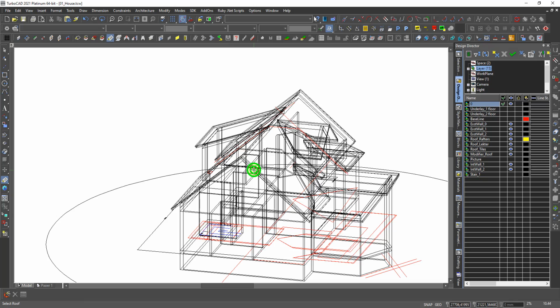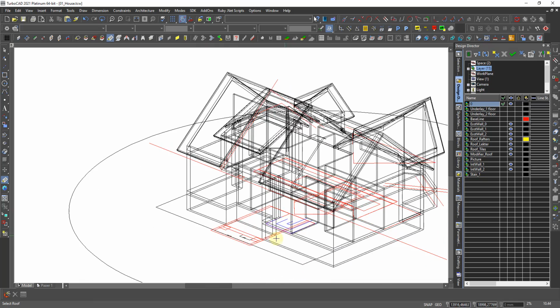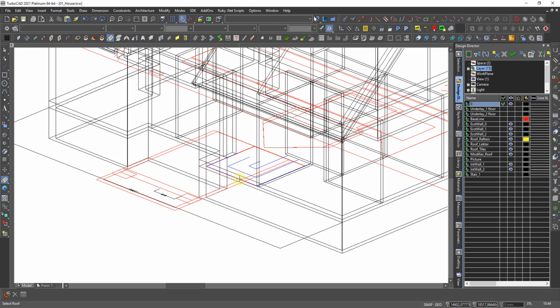The staircase, or stair. The stair standing down here, and we are adding this 2663 plus 220, and say that is the height, but it's not right, because that stair should be lifted up, so it's standing on top of the floor, meaning it should have a total height of 2663.